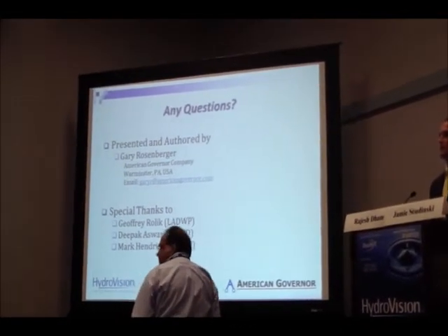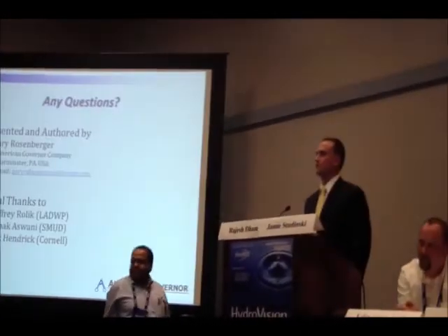Since you have such a good model of your system available, did you consider using a more sophisticated control scheme than a PID controller? Well, in our case with Castaic pump storage, we've found that we generally have the conformance we're looking for, and in that case, we haven't moved to any more advanced control apparatuses. Obviously, they're out there, and they all have pros and cons. So in our case, we thought it made sense to stick with a PID, although it should be noted that in that particular situation, those standard gains did need to be tweaked quite a bit in order to provide a stable system.